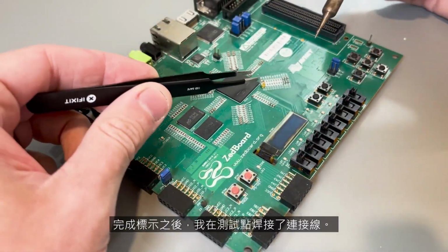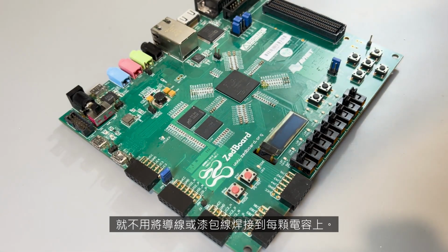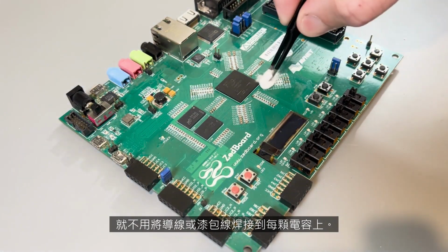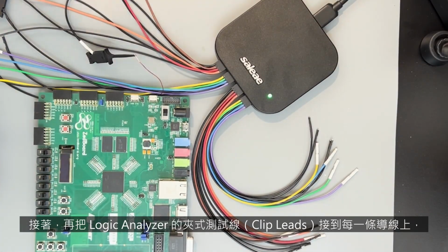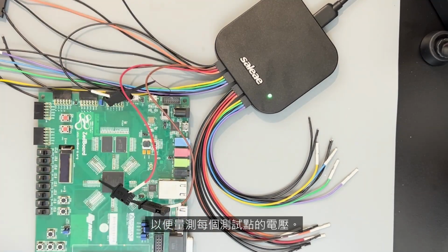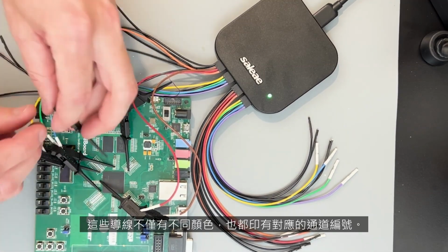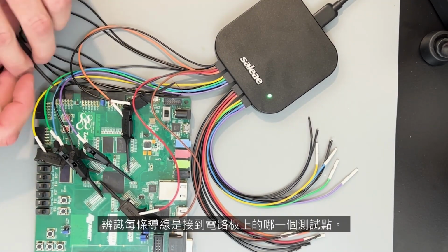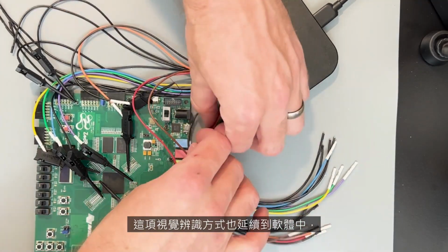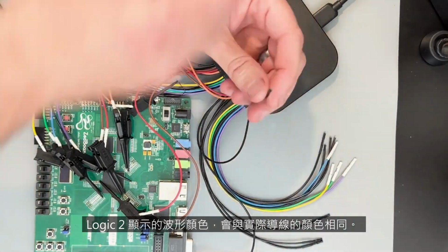After labeling it, I soldered attach points. Now you could use a probe positioner and not have to go through soldering wire or magnet wire onto each of the capacitors, but I chose the magnet wire approach, and then I attached the clip leads from my logic analyzer to each one of those wires so that I could measure the voltage at each one of those points. Now the wires are both color-coded and they have numbers printed on them related to channel, so I have two different ways of identifying which wire is connected to which terminal on the circuit board. This visual clue is carried into the software where the traces actually match the same colors as the wires themselves.